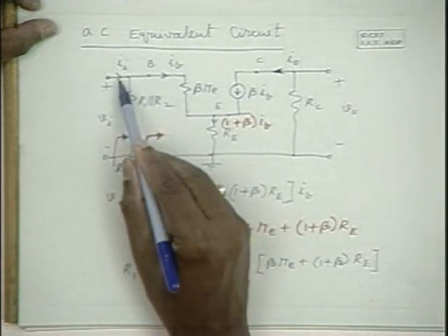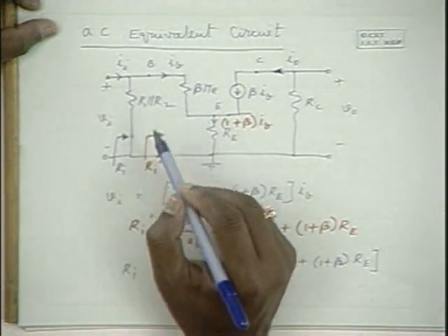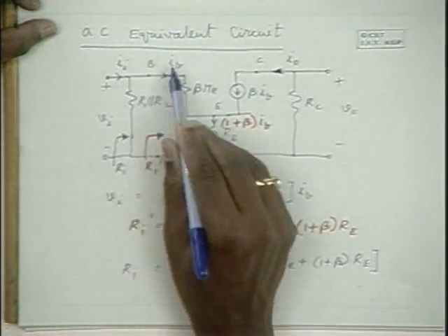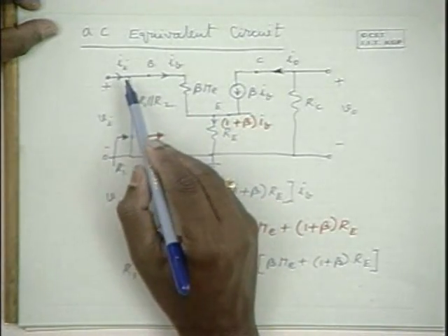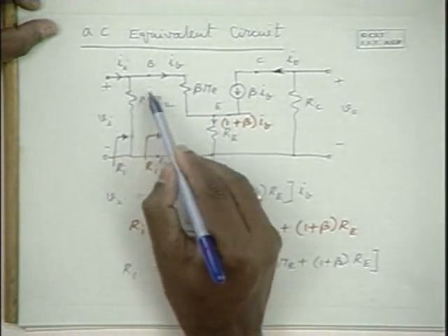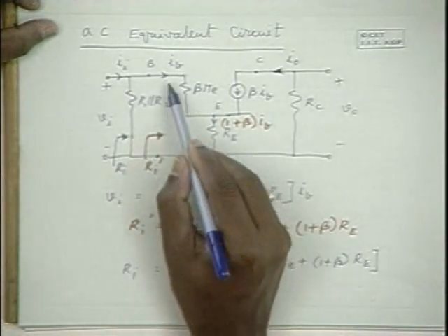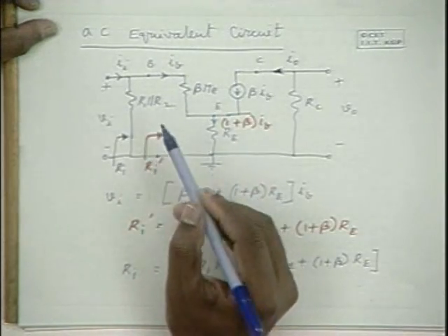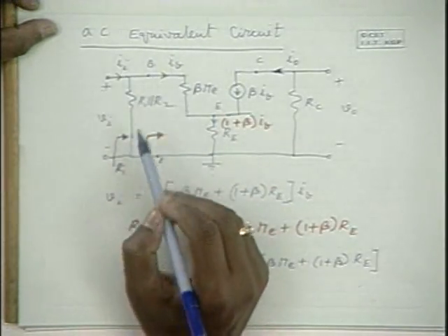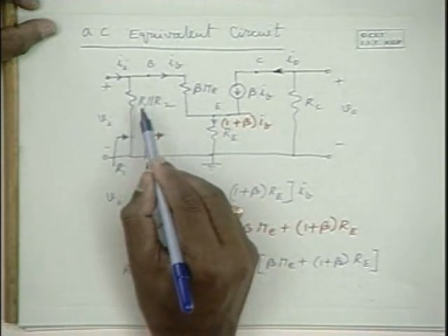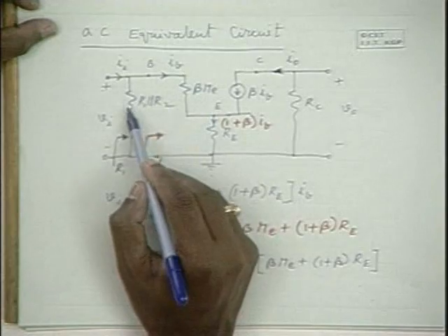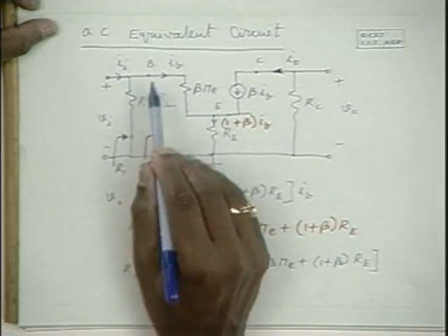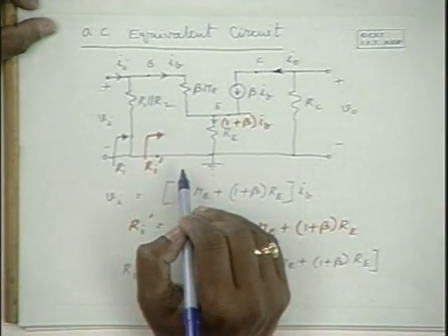Now the Ii to IB ratio can be determined because that is needed in the expression. When this resistance is Ri dash, please note that Ii gets divided between the parallel combination of R1 and R2 and this Ri dash equivalent appearing between these two terminals. Therefore, IB is Ii into the parallel combination of R1 and R2 divided by the parallel combination of R1 and R2 plus Ri dash, because it is the division between these two equivalent parallel resistances.